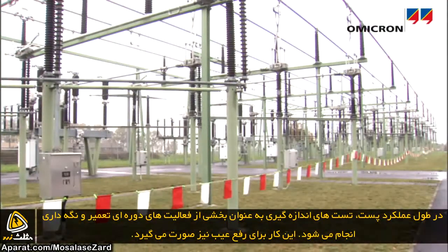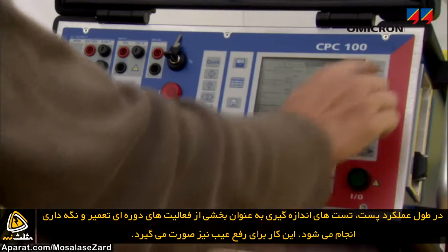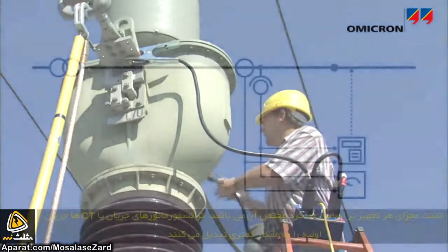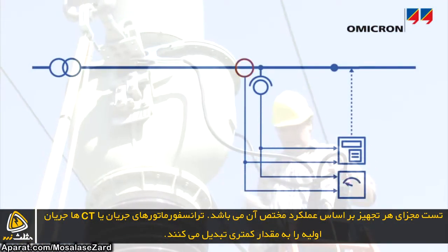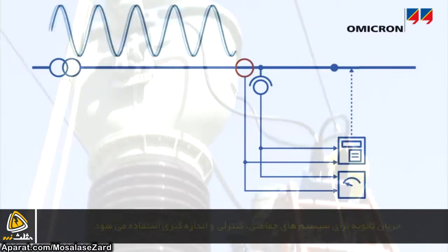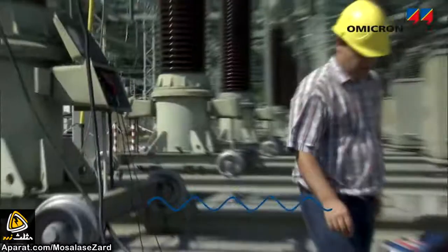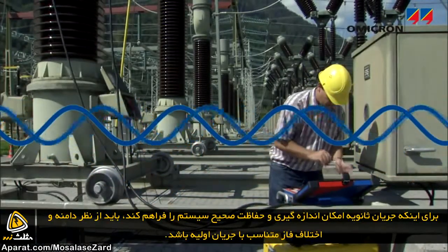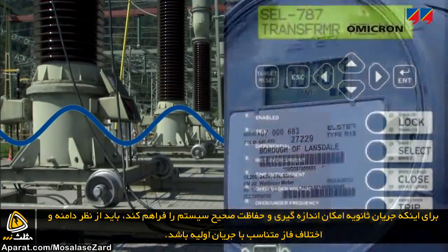During a station's operational lifetime, measurements are performed as part of periodic maintenance activities, as well as for troubleshooting. The testing of individual components is based on their respective functions. Current transformers, or CTs, have to transform the primary current to a secondary current needed for control, protection, and metering systems. The secondary current must be accurate in amplitude, polarity, and phase in order to allow accurate metering and proper operation of the protection system.